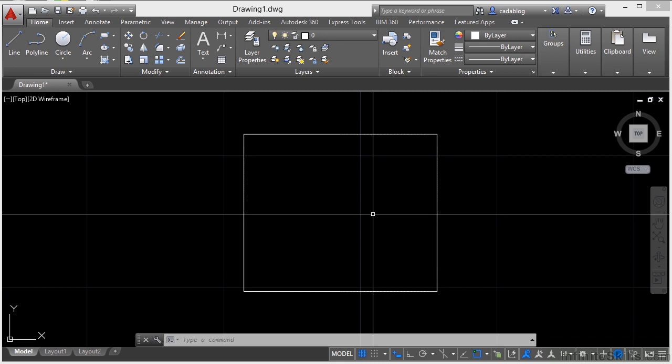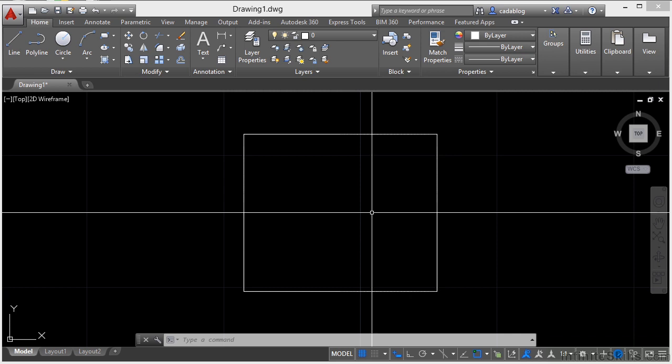There are 2 main spaces that you're going to draw in: model space and paper space. Model space is where your drawing objects go, and paper space is where your annotation and sheet objects go, sort of like a title block or drawing border. We'll cover those 2 spaces in greater detail in another section.